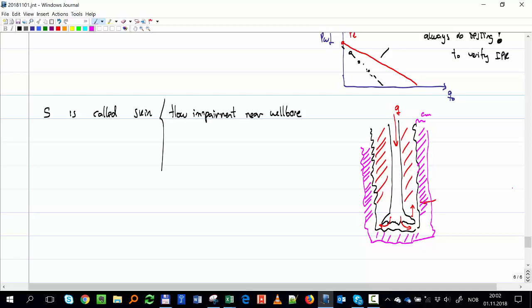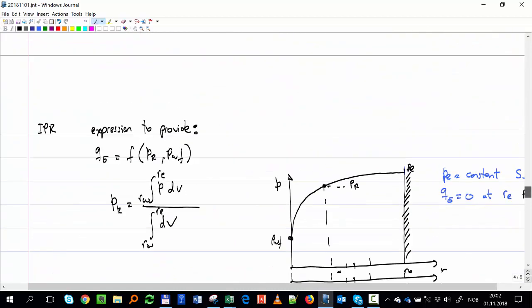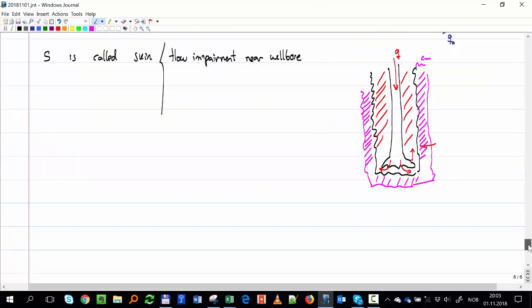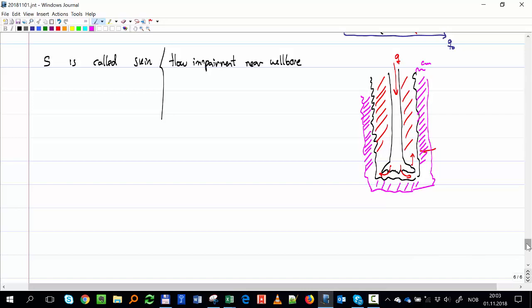And if you remember, what did we discuss just before? For a production engineer, what is really very important is just the region close to the well. And then comes this driller and just takes a dump or something close to that region, okay? So that's why we production engineers don't like drillers too much. So for that case, this is, for example, something that is production impairment. After the fluid comes here, now it has to go through a damage. So that's what we call formation damage.